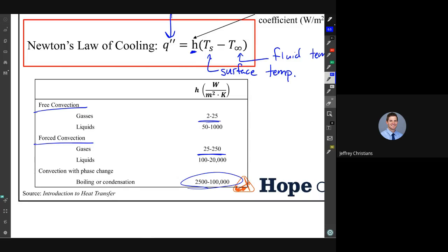I think some of the fanless Surfaces, instead of doing that, have a liquid cooling where you actually have a boiling of the liquid. So you're not going from a free convection to a forced convection, you're going from a free convection to a free convection with a phase change. And that's how you're getting the higher convection coefficients, but you can do that without moving parts and without fans. It's kind of fun.